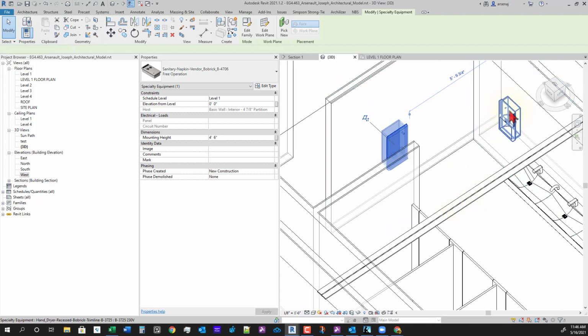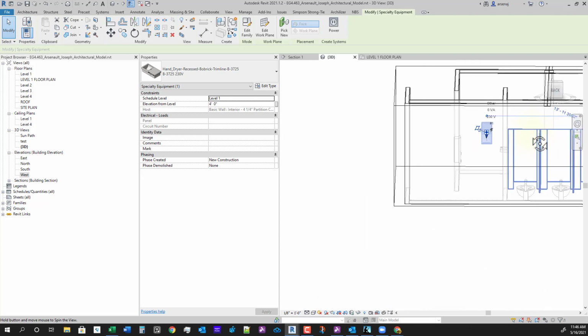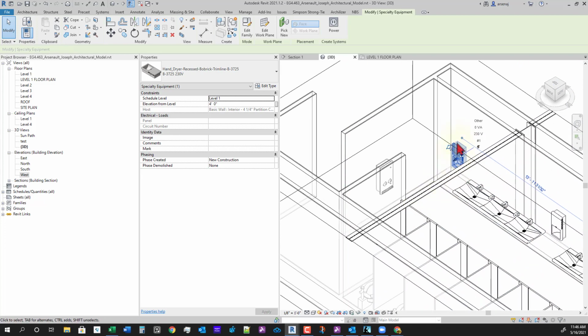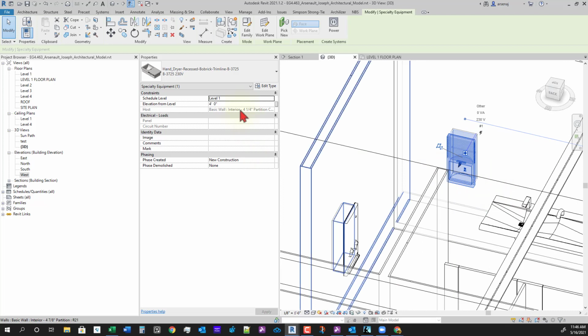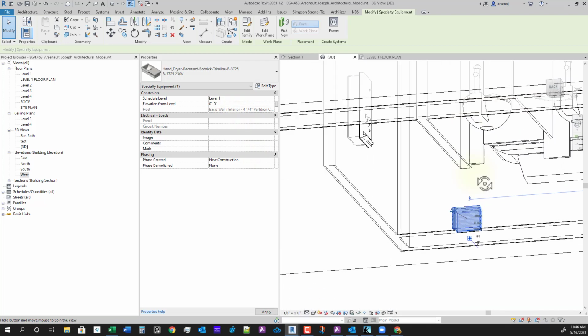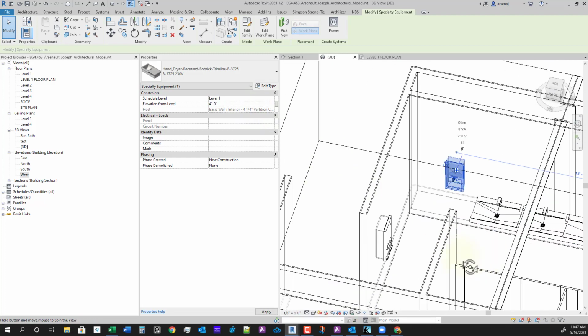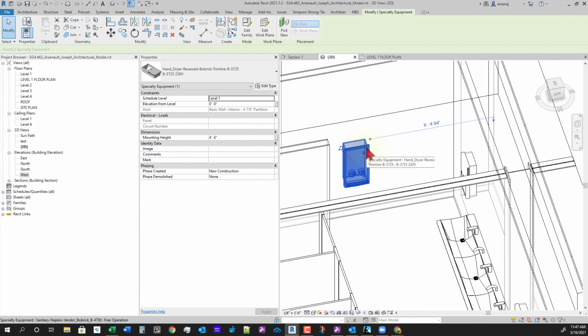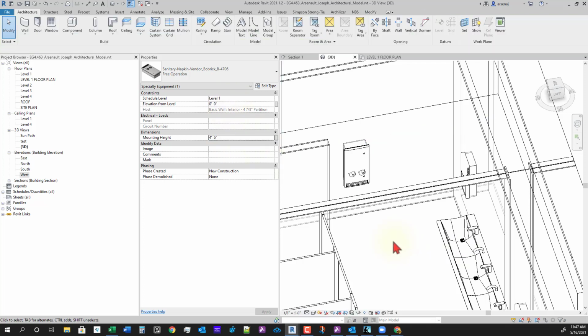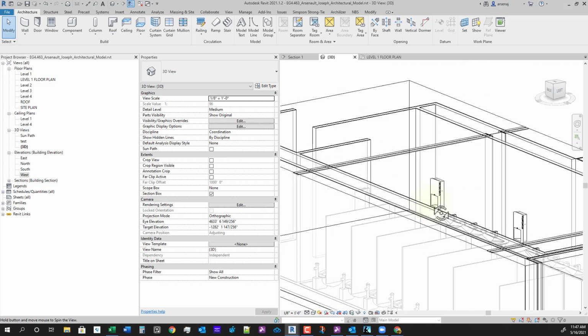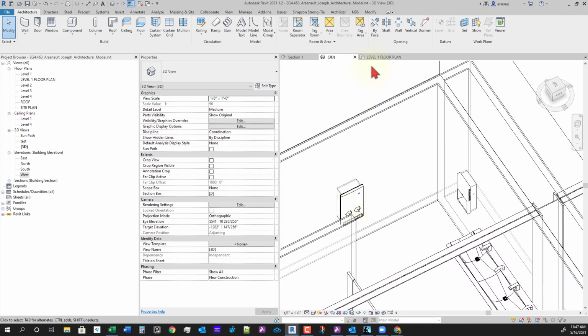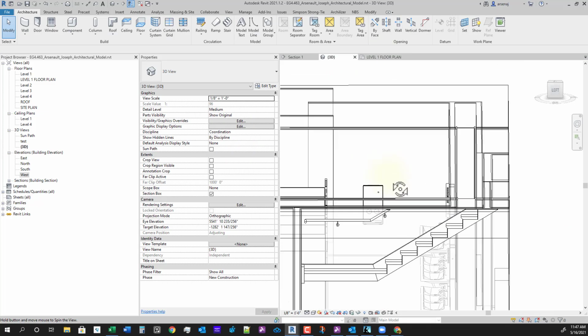So like these are set to be 4 feet from elevation to put it at the correct height. If I were to change this one to 0, it's going to be in the floor. So this one actually has to be 4 feet. And this dispenser will need to be 0 because they've given it a 4'6" mounting height, which is likely, if you were to look at their documentation, the correct mounting height. So, went to our 3D view, fixed that.